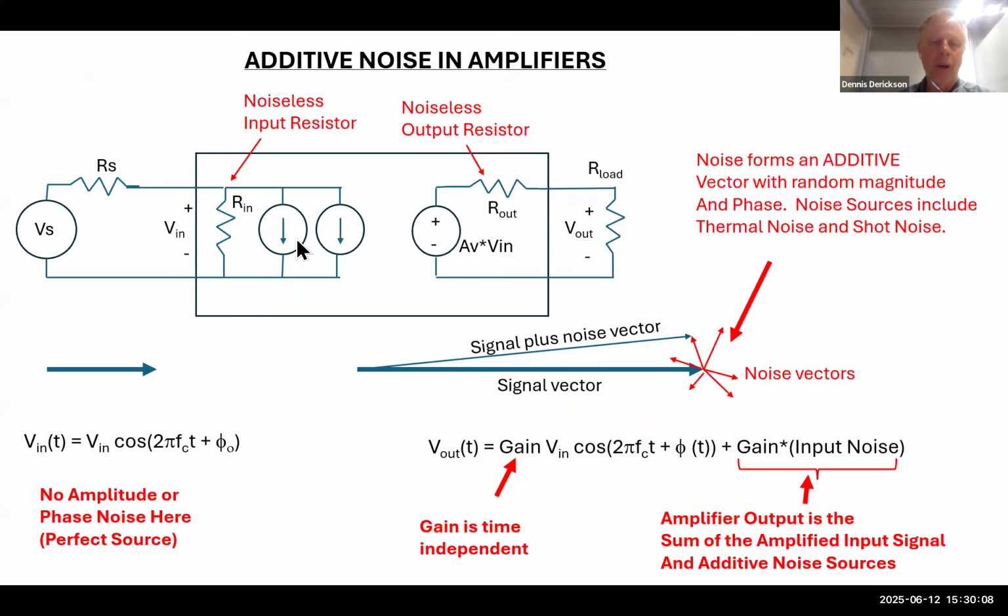So if we have this black box noise model here, where we have thermal noise and excess noise going to the input, amplified to the output, the IQ domain viewpoint of that is that we have the signal right here, which is amplified, which is this long vector right here. And then the excess noise and the thermal noise will be vectors that add in random directions right here.